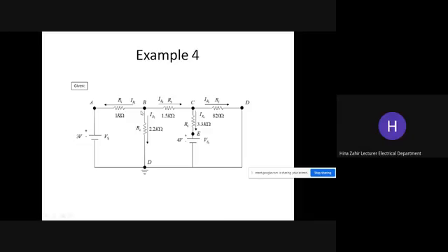So how am I going to write the equation? V1, what is the voltage here? It is not 0. If this was not here, then it would be 0. But what it is, 3. I will say V1 minus 3 divided by 1 kilo ohm. This is our I, first I. Yes, if this was plus minus, then I would write V1 plus 3. But this is minus to plus. So I will write V1 minus 3 divided by 1 kilo ohm. This is actually voltage. Now here, V1 divided by 2.2. V1 minus V2 divided by 1.5 kilo ohm.